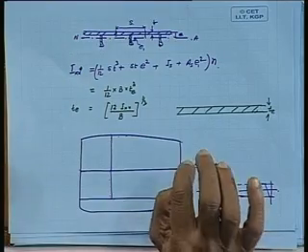The maximum, so it has to withstand that load. Each stiffener will be subjected to a uniformly distributed load, but the intensity of loading will be a function of its position. The lowermost will have the maximum, the uppermost will have the lowest pressure, and accordingly you won't like to use the same section at the bottom and the top, because it is going to make the structure very heavy. That increases the inventory.